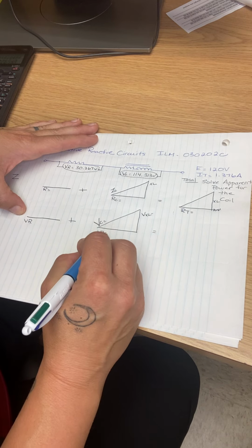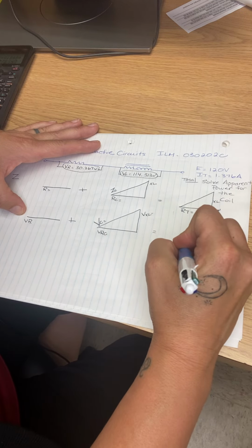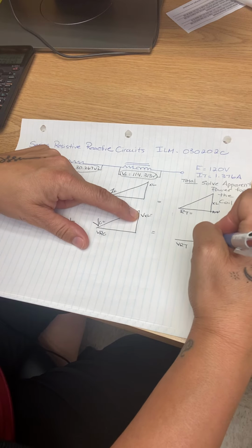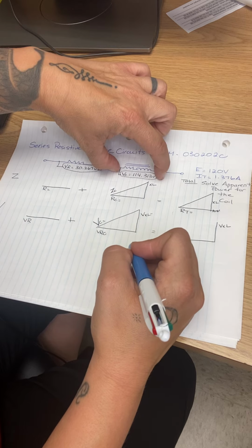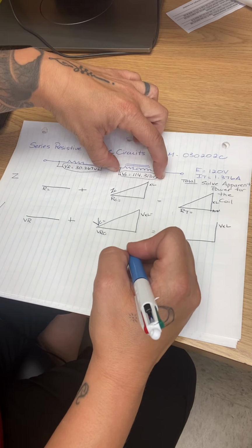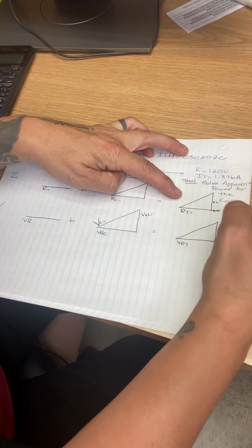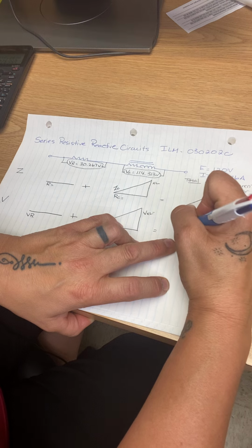Then I can take the volt drop across the resistive component in phase with the volt drop across the resistive component of the coil to give me a VR total. And whatever the volt drop is across the XL component would then be brought forward over to your circuit totals, being that there is only one variable of inductance and there is no capacitance in the circuit. And then the sum of these two sides vectorially added using Pythagorean would give me my E total.